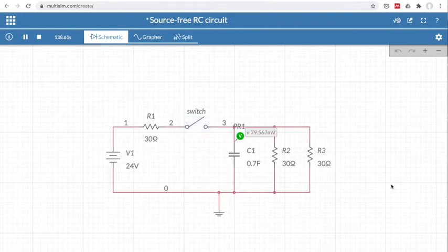At this moment, a few seconds have already passed, and we expect the voltage to continue to lower down to almost zero. What happens to the stored charge is that it gets dissipated to the nearby resistors, since when the switch is opened, these two resistors are the only components directly connected to our capacitor, and thus they absorb and dissipate the energy stored in the capacitor.